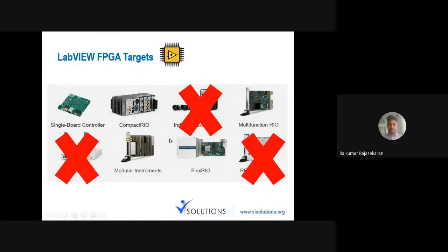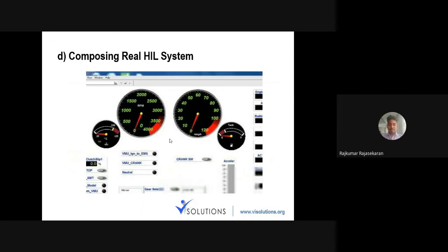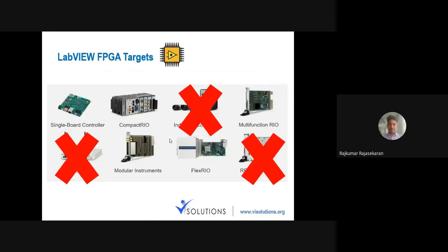This is until the FPGA simulation. HIL is a totally different game. Right now you're doing both simulations in the same hardware. But let's say you want to interchangeably simulate a motor instead of an ECU, or simulate an ECU instead of a motor. In that case, you need to separate both of them into different hardware.